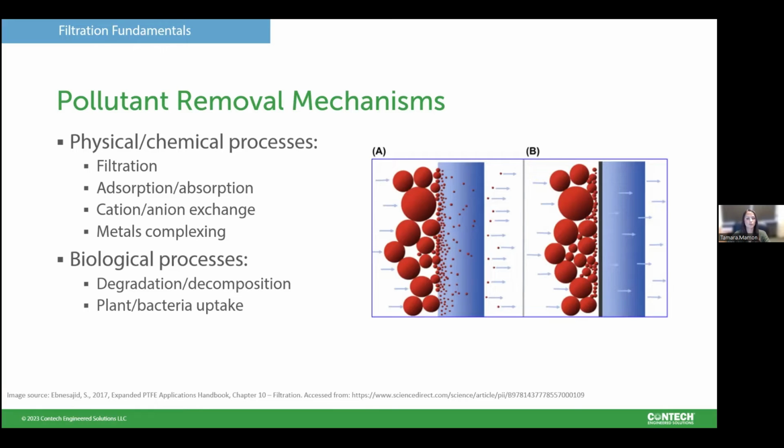So the root zone provides these organisms with a permanent organic food source and a shelter. In exchange, these organisms break down the captured pollutants into soluble forms that the plant can then uptake. Once the plant uptakes these pollutants, it renews the media and leaves that site open for the next storm event.